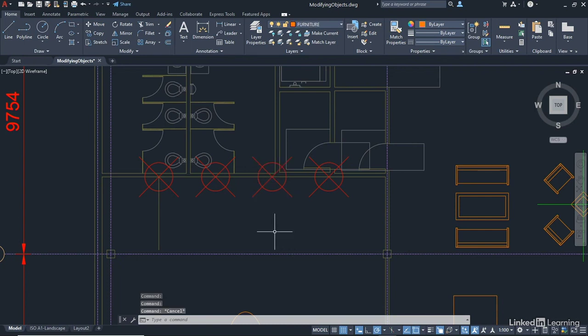Now, you'll remember we set up a point style that was 5% of the relative screen size. Now, they look big there, and of course they would. Now, what we need to do is refresh the view. To do that, you can use the Regen command, which is R-E-G-E-N. Just type it like so, and you'll see it come up on the suggestion menu. When I press enter, keep an eye on those points, and you'll see they go back down to 5% of the screen size. So they're always 5%. You can also save the drawing. That will automatically regenerate the drawing as well.